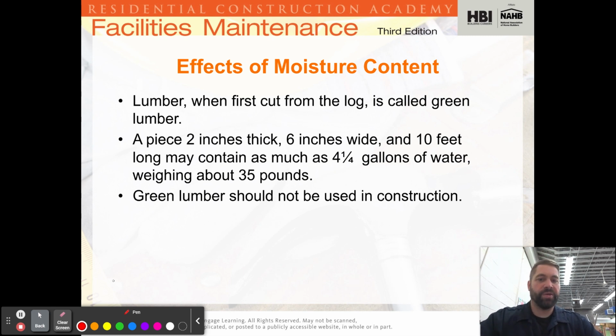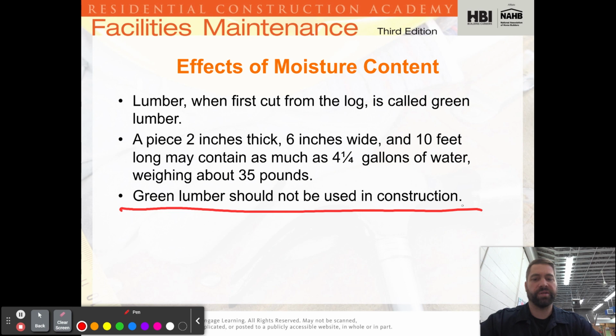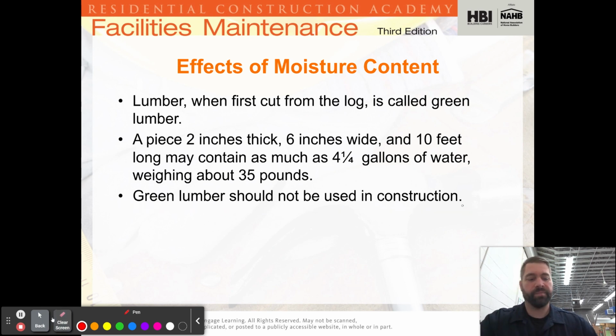Green lumber should not be used in construction. And this is a good point, right? You don't want to use green lumber in construction just because of the amount of moisture that it has and the amount that it can shrink.